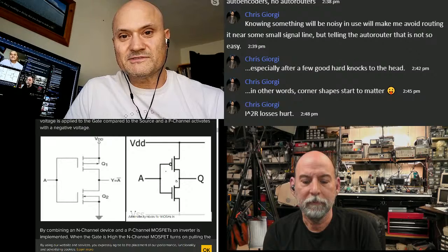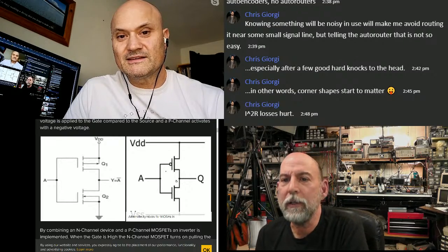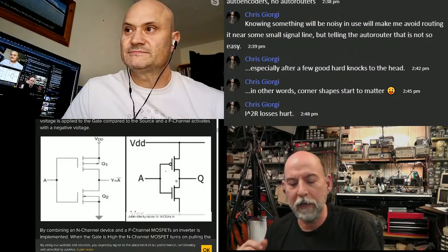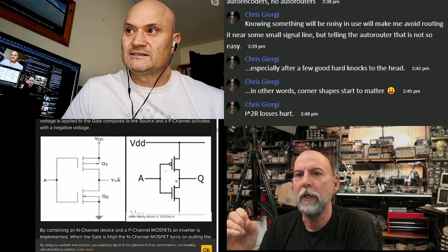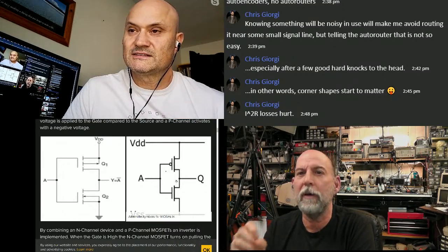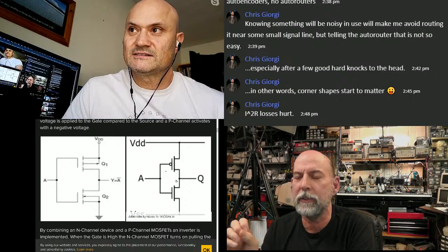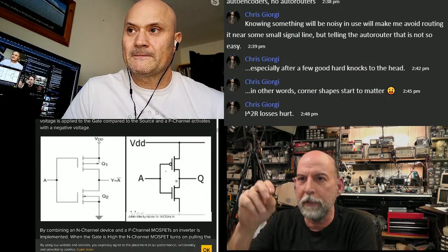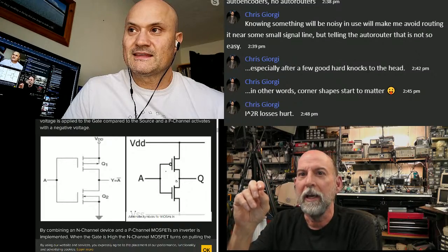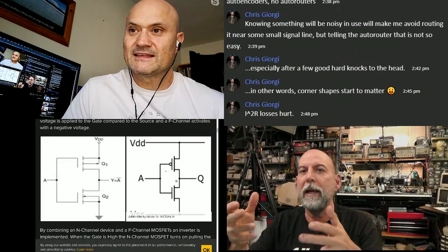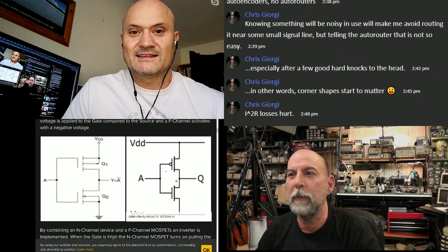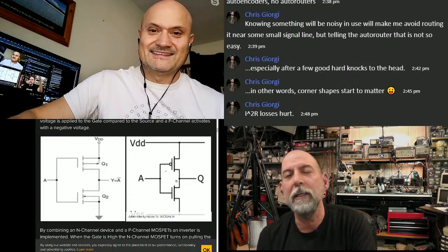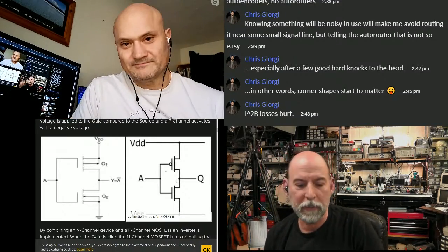that can be frustrating. Well, some really high-level hackers at a hardware level learned that they could take chips that have supervisor modes, or an unreadable identity, and play with the voltage. They take a 3-volt part and run it at like 2.2 or something, and they get it into a funny mode where now they can read the part you're not supposed to be able to read. So they actually use low voltage as a hacking tool on some processor-based stuff.